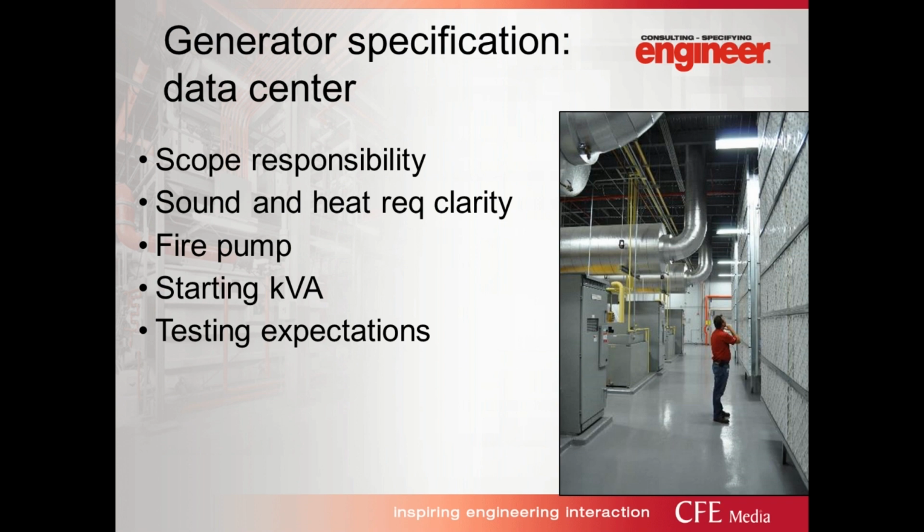So some things that we see as hiccups that we always try to mitigate, first would be scope responsibility. Again, it's not just an electrical machine. And if it's not packaged and you have it indoors, there's a fair amount of controls and mechanical work that needs to go on as well, as you can see in the picture here on the right. So you really need to have a joint effort with your electrical and your mechanical engineers for how to specify this properly, calculate it properly, and then be clear on your documents about which contractor is doing what bit of work.